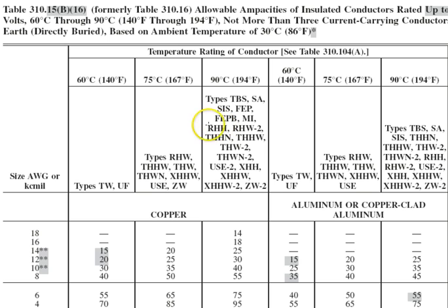Which cable are we using? Well, I'd say 99.9% of the time you will be using a 90-degree rated cable. So this is typical of what we use in PV systems. However, especially with residential systems, the equipment that we're actually tying into is 75-degree rated. For commercial systems, occasionally you'll find some 90-degree rated equipment.